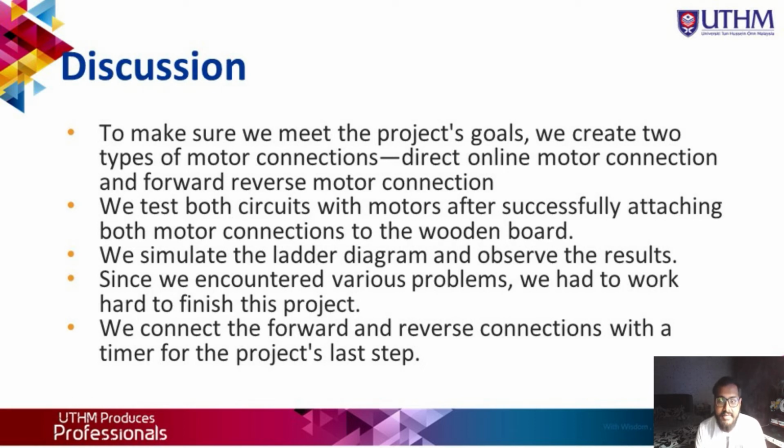For the last part of the project, we connect the forward and reverse connection with the timer. The ladder diagram is simple, with the timer added. When the button is pressed, the PLC issues the command. A timer which was established using the ladder diagram is also initiated, and it will begin a few seconds after the button is pushed. The motor will turn off when the stop button is pressed.